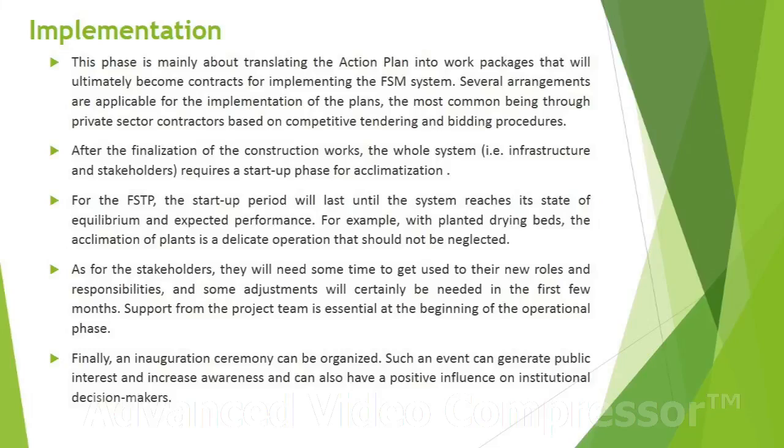After the finalization of the construction works, the whole system, that is infrastructure and stakeholders, requires a startup phase for acclimatization. For the FSTPs, the startup period will last until the system reaches its state of equilibrium and expected performance. For example, with planted drying beds, the acclimatization of plants is a delicate operation that should not be neglected.